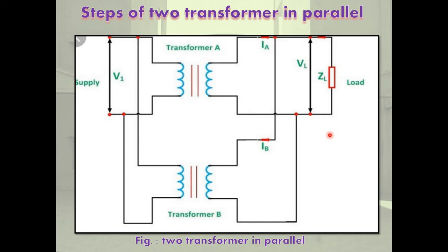In case of overheating, the transformer should be switched off from service immediately, but cooling fans and cooling water should be continued till the oil temperature falls to normal. Then the transformer can be switched on again. This is the important point for overheating of transformers. These are the basic details of the transformers.